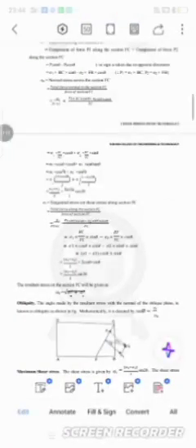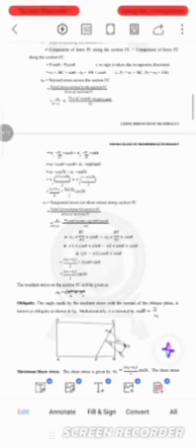When we solve the wedge, we can find out that the total force normal to the FC is equal to the component of force P1 normal to the section FC plus the component of force P2 normal to the section FC. Simply P1 cos theta plus P2 sin theta. Finally, we can get the resultant force is equal to root of sigma n square plus sigma t square.